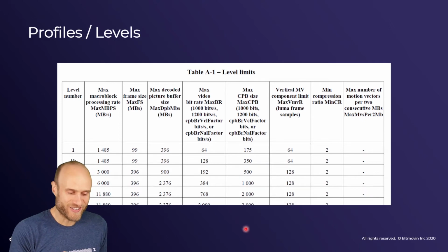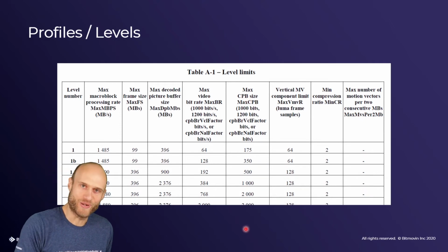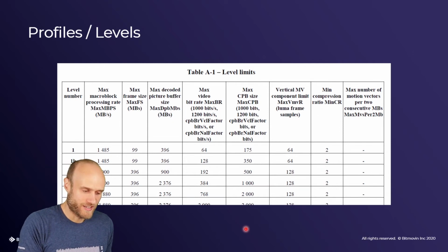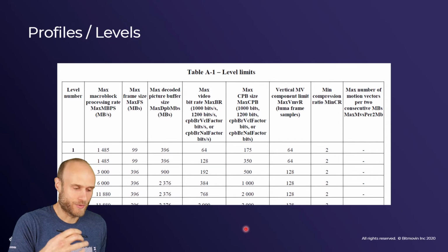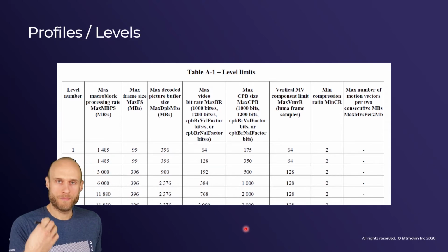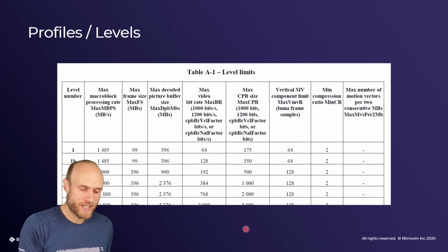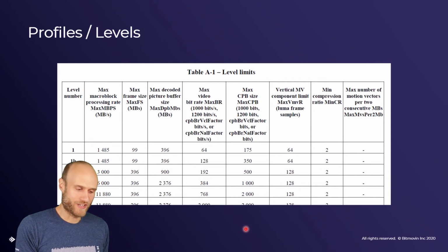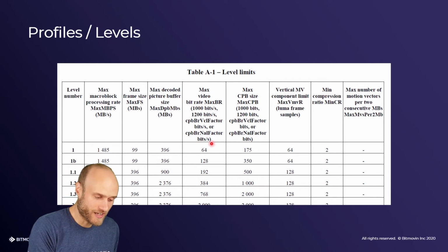And those are exactly the values that I just talked about. Those are the buffer rate, the HRD buffer rate, and the maximum size of the HRD buffer. Those are these values. So my main point here is, if you get a bitstream and somebody says, please verify if this adheres to a certain level, you can easily check the other values.